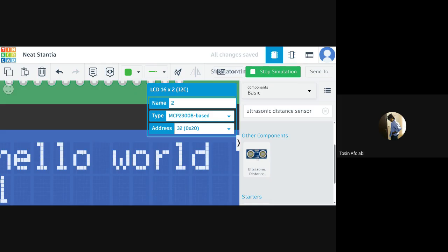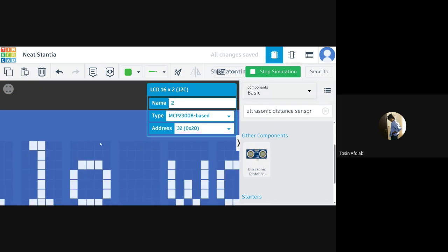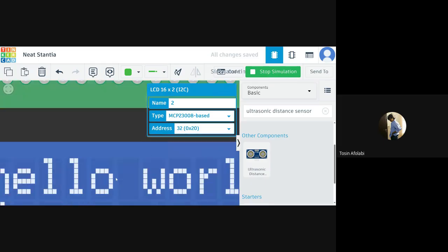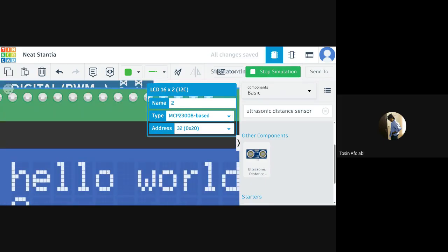Okay, now I also mentioned something about 40 pixels. That's 5 by 8, which is what each section has. If you count, you can count 1, 2, 3, 4, 5, then 1, 2, 3, 4, 5, 6, 7, 8. You can always count 8. That's 40 pixels each, as I explained earlier. That means you can form any character, including symbols, letters and numbers, as this is showing. Any questions so far?